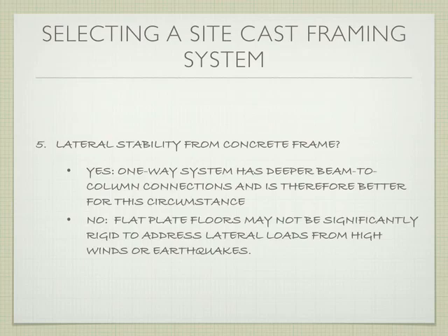So if you live in one of those new houses that has those "do not drill into the floor" stamps, this is the kind of thing that could happen if you started drilling into the floor, because you'd relieve that stress that's holding the whole slab together, and cause the tendon to shoot out one end or the other, damaging your neighbor's property and that sort of thing.